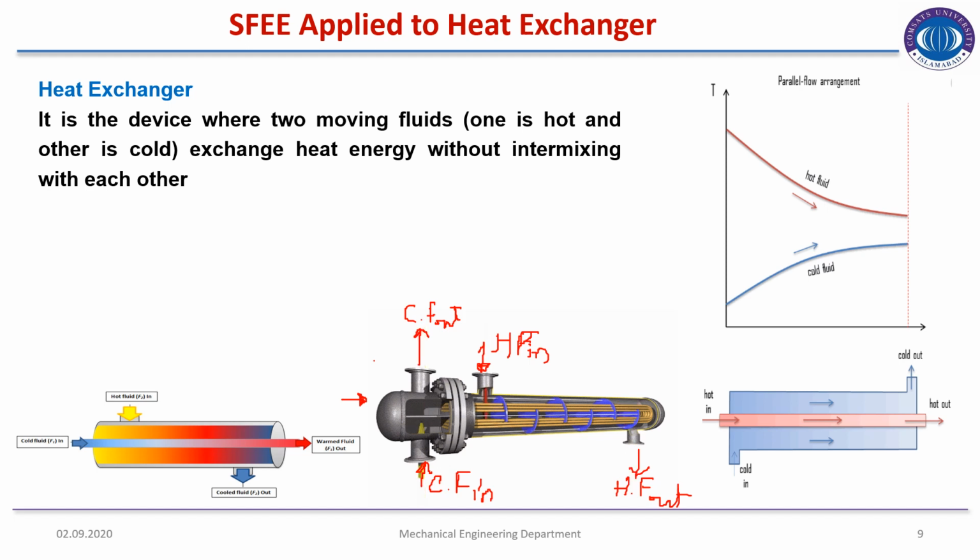These are the inlet and outlet of the heat exchanger. This is known as the channel head. Tube bundles are shown in yellow. These are baffles, to restrict the flow or decrease the velocity, so there is greater time for heat to exchange. That is an industrial heat exchanger.